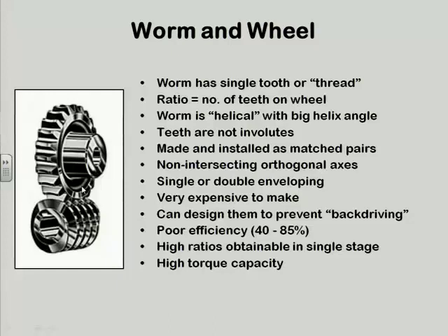But if I've got crummy efficiency, I'm going to have to turn a lot harder on that worm to turn the same load that's on the worm gear, right? So I've got some load on the worm gear that has to be delivered, the torque that I'm delivering to the load. And if I'm 100% efficient, I can just put 1/20th of that in up here, right? 20-to-1. If I'm 50% efficient, I've got to put in another half up here to make up for the losses, because that stuff is leaking out the sides. Essentially, I'm putting that energy out the side of the gearbox as heat. And I've got to put it in there, but not all of it comes out on the shaft, right? That make sense?